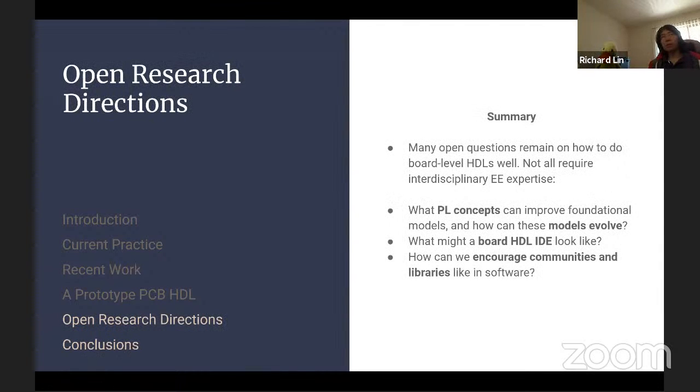Right. So in our prototype system, we had a reasonably strong type system. I mean, think of it as analogous to Java rather than Python. So when you tried to compile a board, if you made connections between incompatible ports, it would just fail to compile and tell you, you can't connect a voltage source to a digital sink.